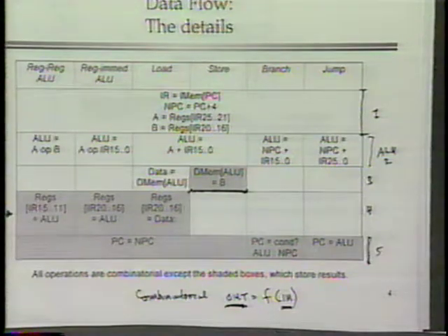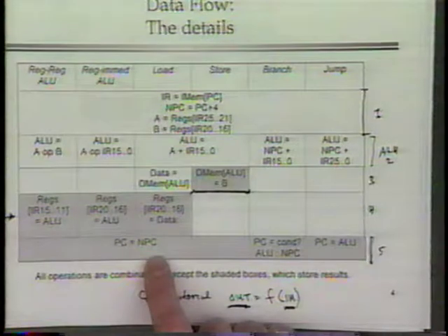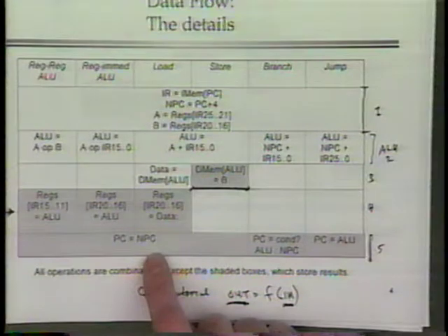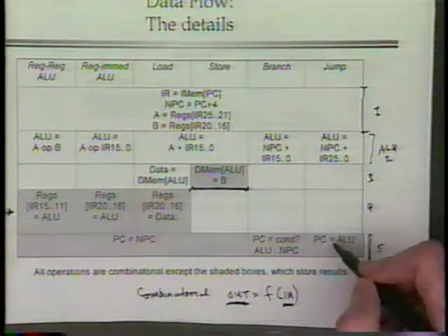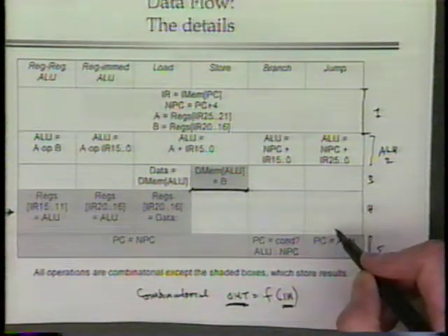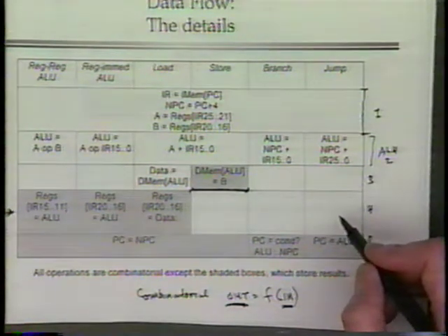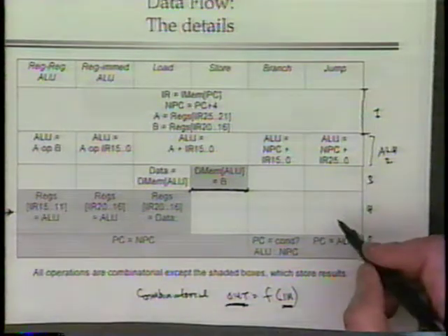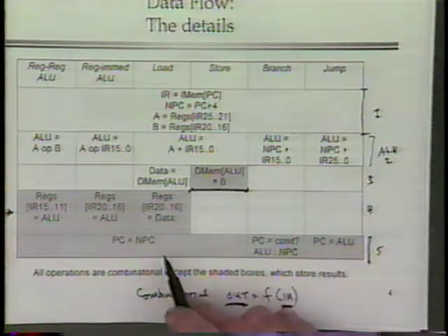Come on, somebody. Well, for one thing, some of the PC calculation can be done earlier, like for example on the way right. If you go to the right hand side, there are empty pipeline stages where that can be filled in. Okay, that's one thing. You could consider moving these things up. But remember, you've got to be careful so that 2 instructions don't try to use the same resource at the same time. But yes, that's one reason why this isn't great. You can move some of these things earlier.